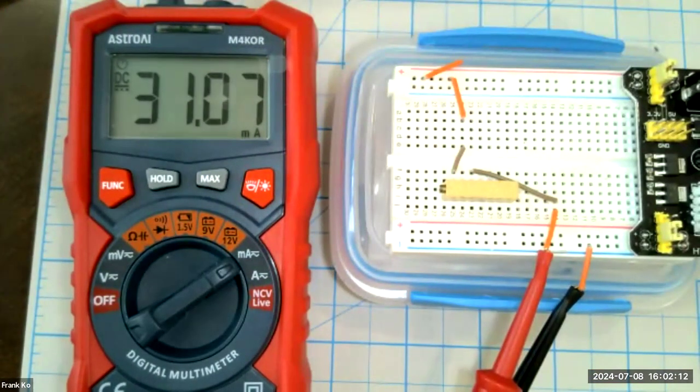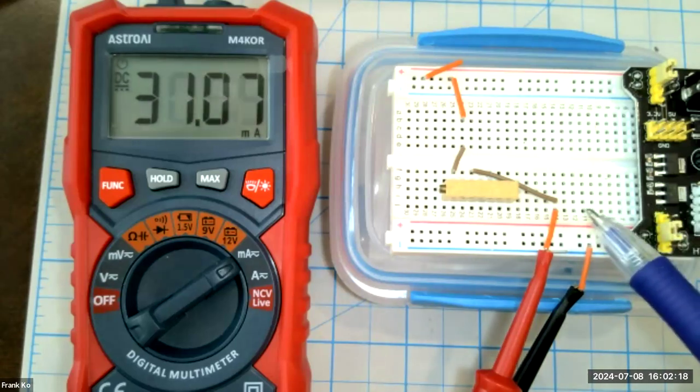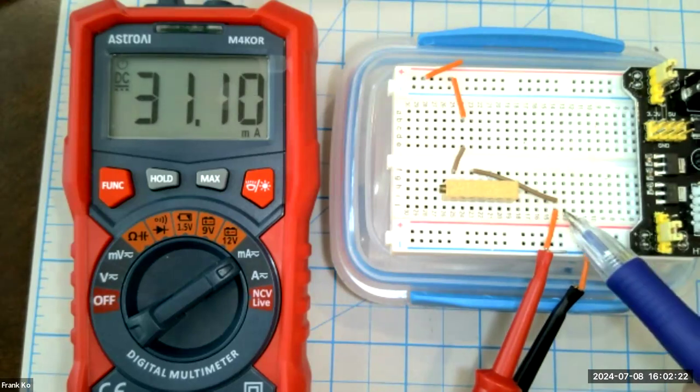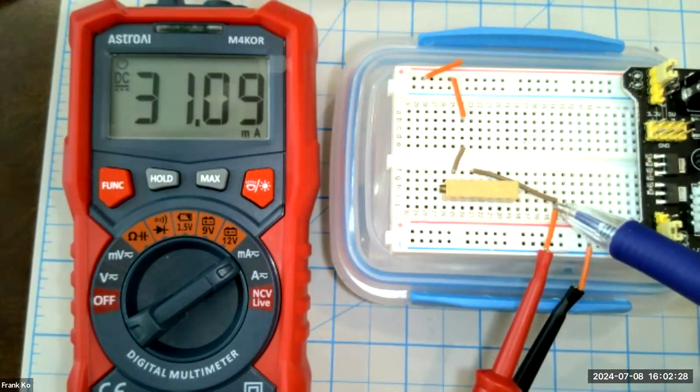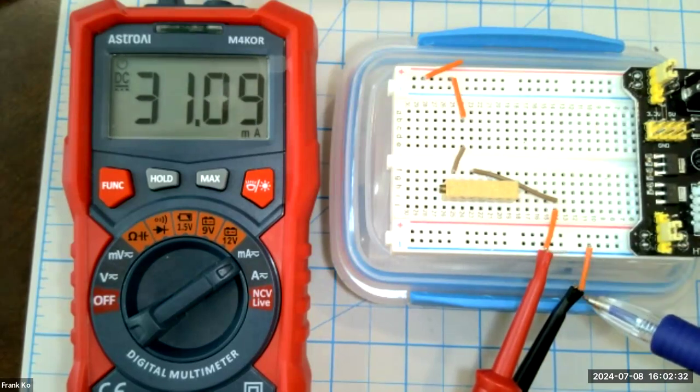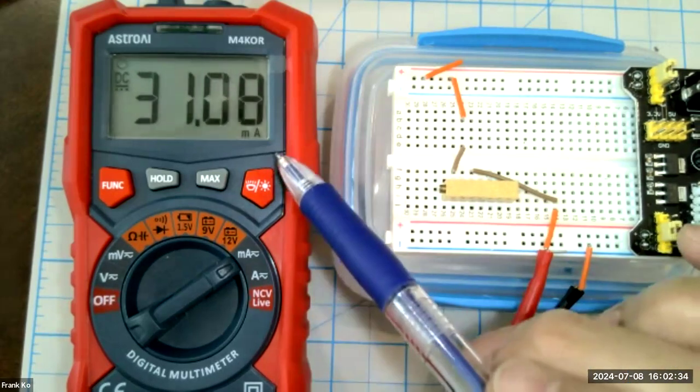So as you can see, I've wired the circuit to create an open at the bottom of the circuit to measure current. So this orange wire was previously connected directly to the blue rail. So I've broken that open, detached it, and then made a connection here. So my open is between this point and this point, to which I attach one ammeter lead and the other ammeter lead, and my current is showing